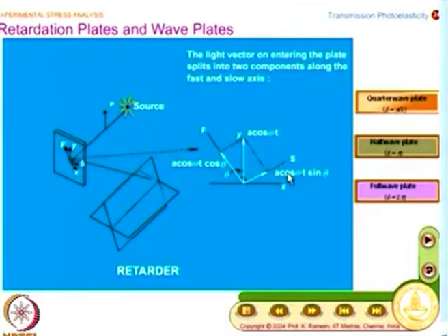We have also looked at how photoelasticity gives you sigma 1 minus sigma 2, and then it gives you the orientation theta. You have answers for that in this slide. One answer is, when I look at the fast and slow axis, they could be thought of as coinciding with the sigma 1 and sigma 2 directions, and this is your theta. So, if you find out theta, you get the principal stress direction, and we have been talking about delta, that is acquired within the crystal plate, and whatever delta you have acquired is nothing but sigma 1 minus sigma 2.